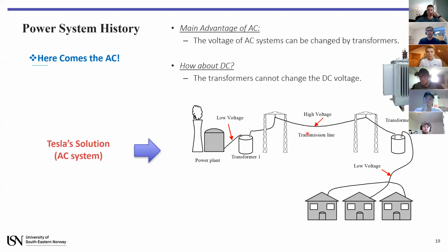Yes. And in the simple equation, sorry for that writing, for a simple R, the loss is R i square, R i². So when you increase the voltage, you decrease the current, so you will decrease the loss in the power in the transmission lines.